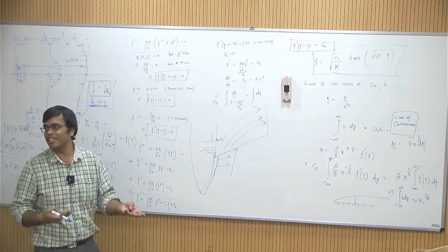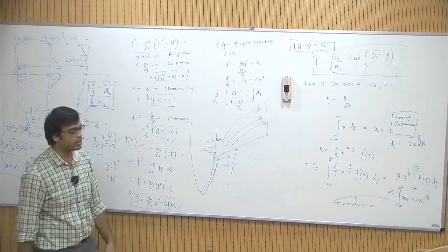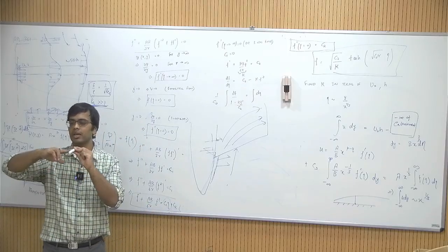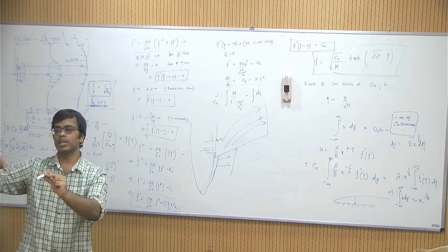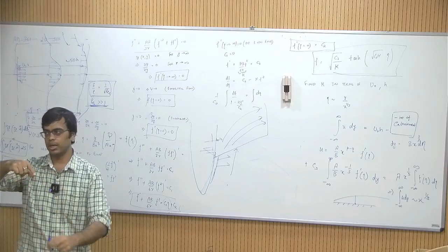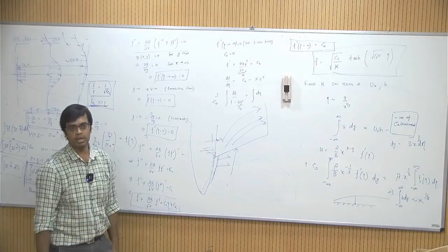It is not just a wing that is flowing, the whole body of the airplane is flowing. Okay. So, if you imagine this as the airplane and this as a wing, as the plane moves in this direction you have a boundary layer that is forming and that is resulting in a flow outward. Okay. And that is giving you the 3D flow on the wing, 3D boundary layers on the wing.